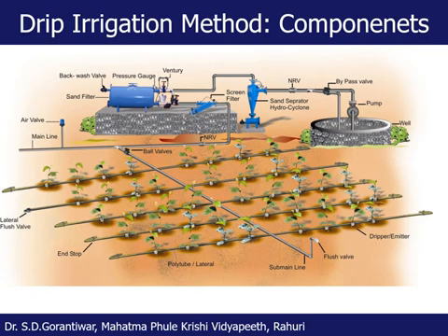which is shown here. This is known as the sand filter. Now what is the purpose of the sand filter? Basically, the sand filter is used to separate any organic material, algae or debris, or say leaves and all other things which exist in the water, because the hydrocyclone filter cannot do this.